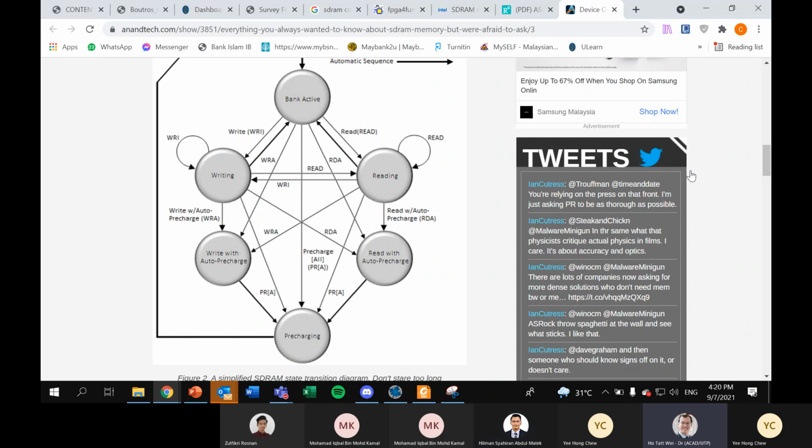You have to study and obey the timing because you are doing this on a real chip. There are certain timing requirements, and that's what makes this hard, because it's no longer like your digital electronics where everything is just a clock cycle. So you have to choose your clock. You might have to bring down the clock, or maybe generate multiple clocks. So it's up to you.